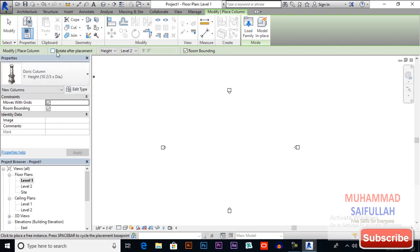You can rotate it after placement if you want. I will do it later in this video. Also you can specify its height and depth, from level 1 to level 2. Room bounding we will discuss later. It works as a quantity tool.